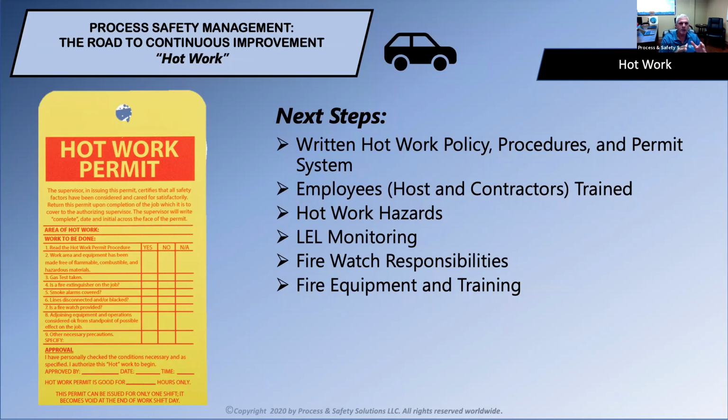Making sure that your employees understand the hot work hazards, making sure that they know there's potential for fire at elevated locations, and making sure that if they're doing work on a roof, there's proper protection, not only in that specific area on the roof itself, but any adjoining areas or even on ground floors. Making sure of LEL monitoring, or lower explosive limit monitoring, but that goes beyond just LEL monitoring. There might be other hazardous atmospheres that have to be addressed as well. And making sure that the Firewatch understands their responsibilities.